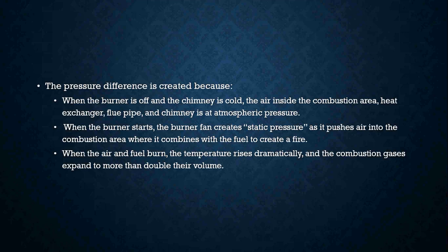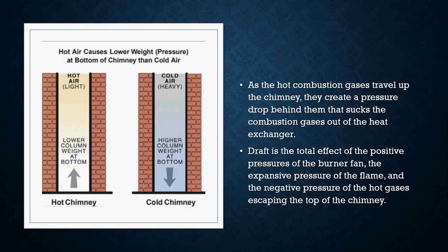When the air and fuel burn, the temperature rises dramatically and the combustion gases expand to more than double their volume. As those hot combustion gases travel up the chimney, they create a pressure drop that sucks the combustion gases out of the heat exchanger.